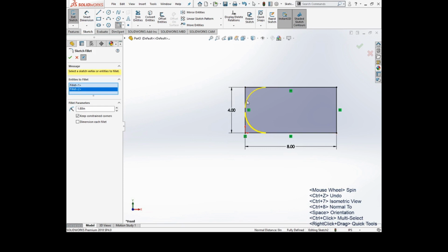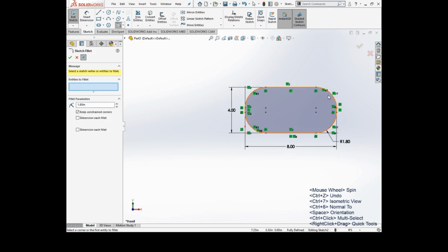When you create a fillet, the fillet will shorten the length of the side, so it will no longer be equal, and it'll break some dimensions. It's fine. Shouldn't be too bad. And so if we select all our sides, it will essentially just round the corners based on a circle of the radius that you set here. And there we go.